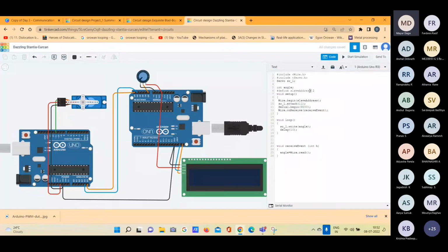It is not necessary that this should be the same as that; only the addressing binary code should match. So this will send the address through the SDA line. The slave will receive that, and since I2C has the acknowledgement feature, it will send back an acknowledgement message, which we are not interested in for now.